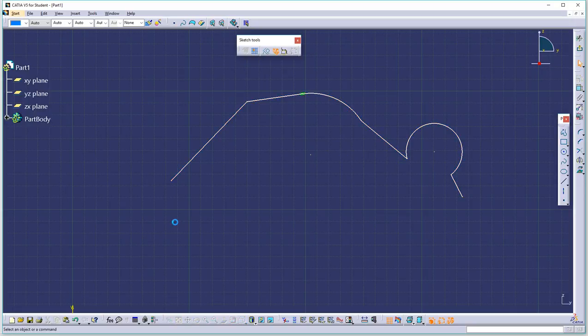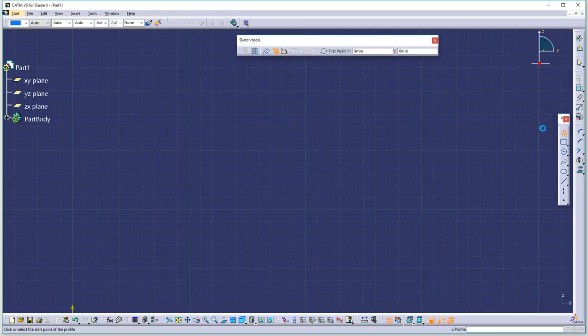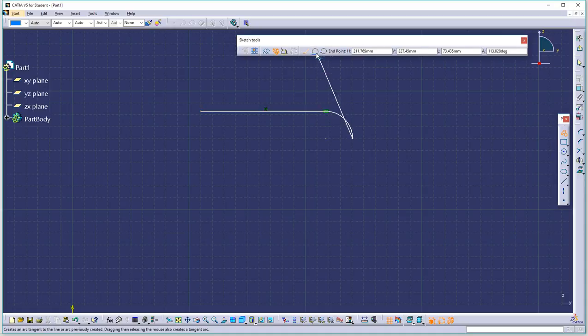Okay. Now let's do this again. And let's keep in mind that we already have our geometric constraints on. So watch what happens here. Tap, make it horizontal, sloppy drag. It puts me into arc mode. Let's try to get this right there as horizontal, vertical. Now notice it made a tangent constraint there because I was on the tangent button. Now I'm going to, oh, look at there. There's a tangent again.